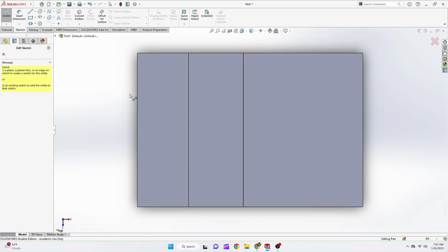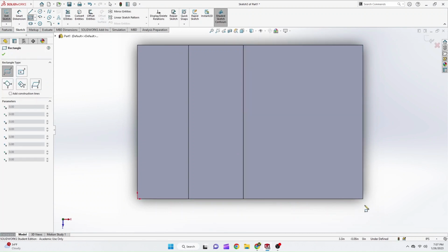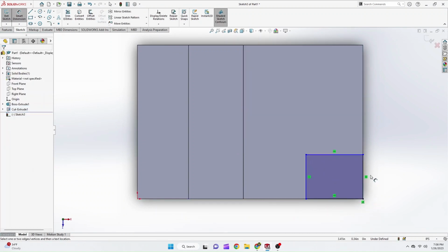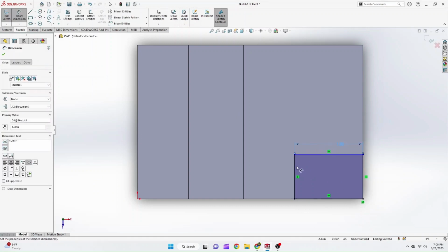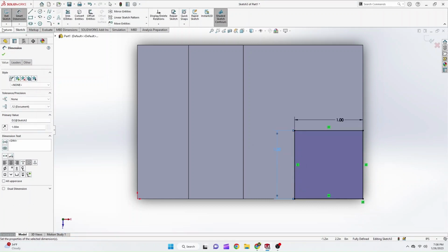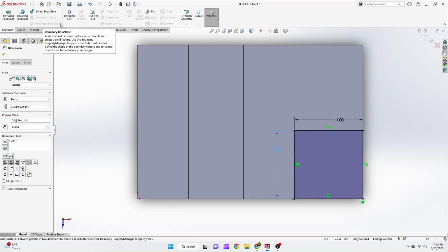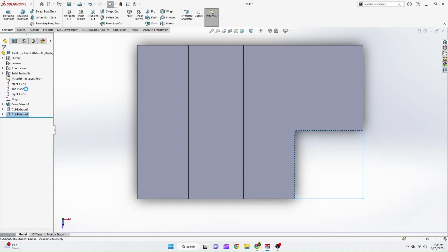Then we're going to go to our sketch, corner rectangle. We're going to click on this plane as our reference, and it's actually going to readjust us. It's really nice. And then we said earlier that it's a 1 inch by 1 inch. And then one more. And then we knew that it cut through all, so we didn't have to mess with flying around. And we could just do the blind with its 2.25 inches, but that will do it.